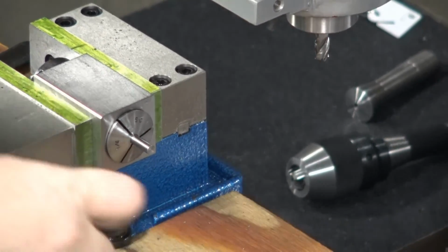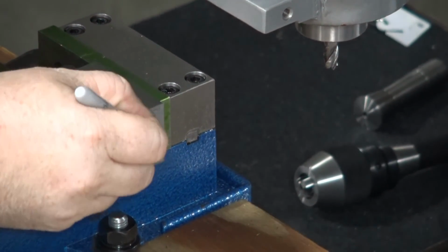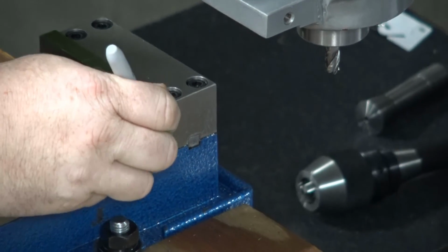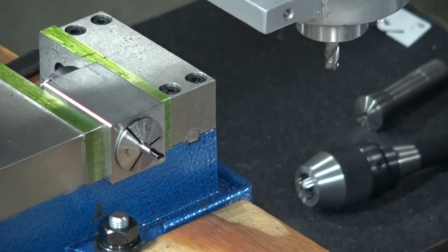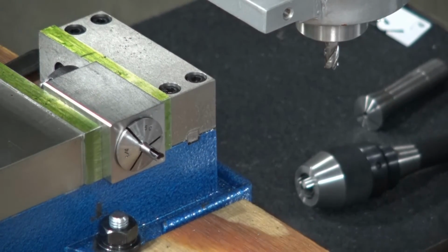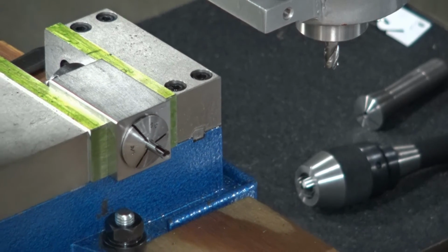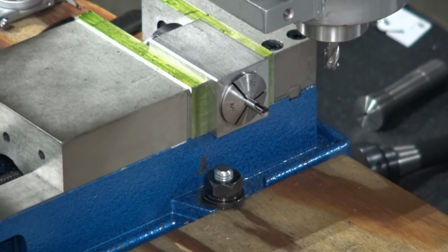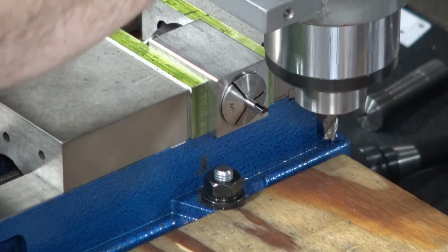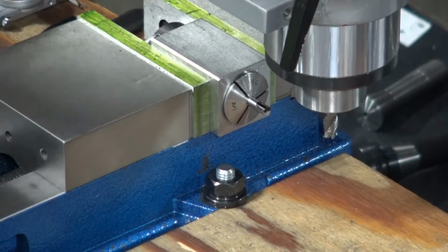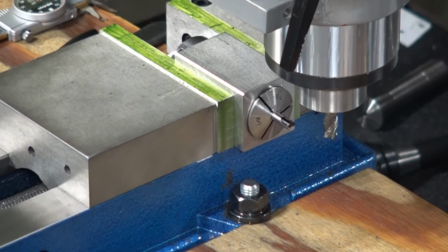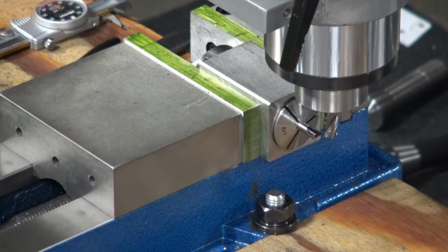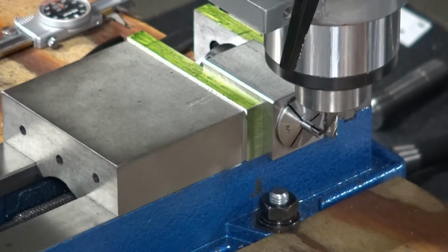I don't run out of travel while I'm in the middle of the cut, because that would be bad for me. Before I start coming down closer to my workpiece, I'm going to color the top surface. And I'm going to color the end, okay? We had discussed using the paper trick to reference off the end. I apologize, but you'll have to get one of the other instructors to demonstrate that to you if you're interested. For the simple fact that with me missing that arm, it's hard for me to hold on to the paper and dial the hand wheel all at the same time.